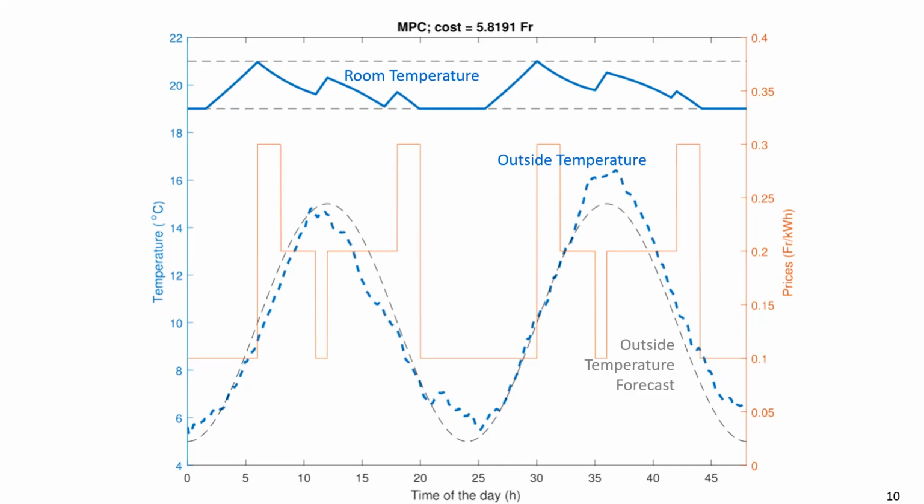We just put the cost function, the system model, and the MPC does the right thing here. We see also that day 2 and day 1 are very similar, but are not the same. For example, at day 2 here, the decisions that were taken led to a slightly different state of temperature here, because the outside temperatures were different. So this is an illustration that the MPC is taking decisions that may vary based on the actual implementation. So it adapts to the MPC forecast, but also adapts to deviations from forecast.